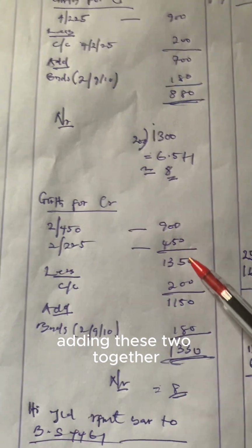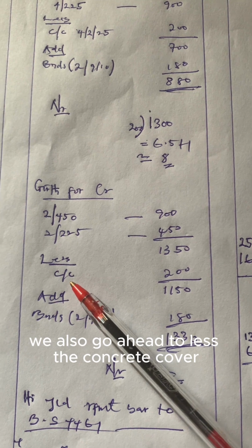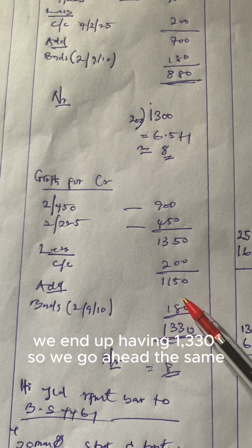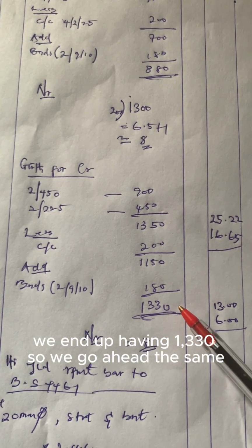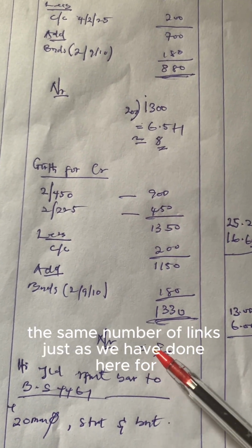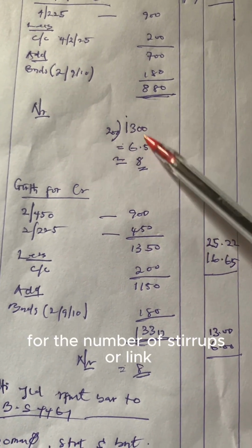Adding these two together, we have 1350. We also go ahead to less the concrete cover, which is 200. We add our bend, which is 180. We end up having 1330. So we go ahead with the same number of links, just as we have done here for the number of stirrups or links.